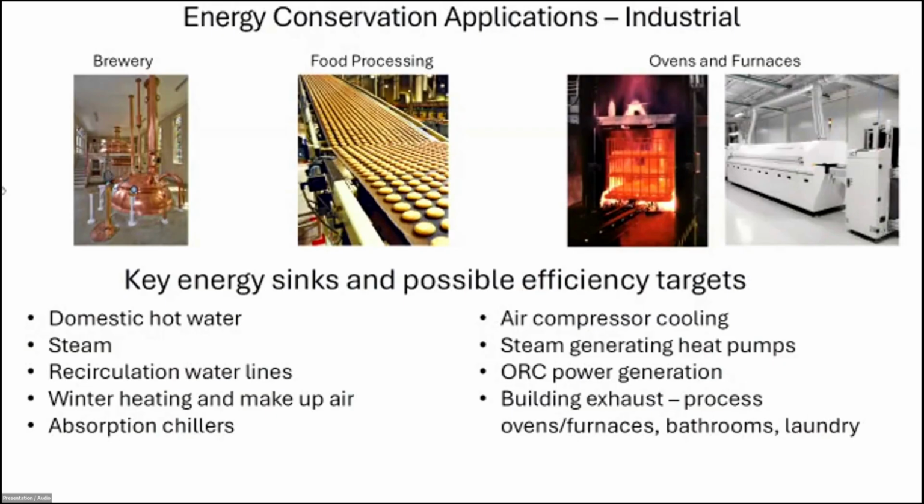So what this group is looking to do is harvest waste heat energy out of that thermal oxidizer, feed it into the ORC machines to generate roughly 3 megawatts of on-site electricity for themselves. These are very, very resilient machines. These are not heat recovery steam generators that require a clean source of water. They are completely enclosed, and for an application like this in the remote areas of the mountains, it can make a really, really big difference for them.